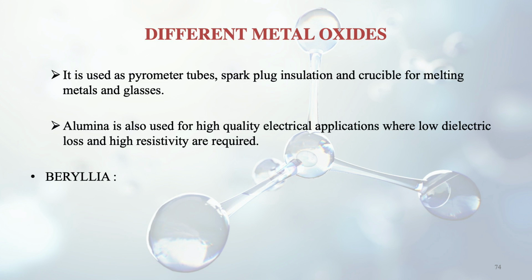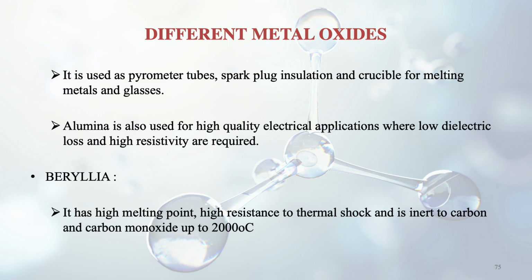Further moving on, we shall now discuss beryllia. It is beryllium based. It also has a very high melting point, high resistance to thermal shock, and is inert to carbon and carbon monoxide. This property of high resistance to thermal shock and its inertness to carbon and carbon monoxide is very useful, especially up to 2000 degrees centigrade, because then there will be no reactions.